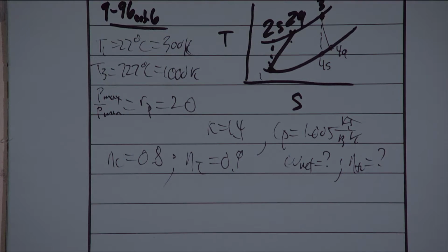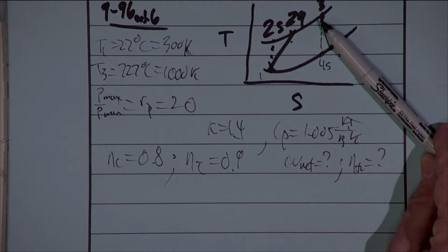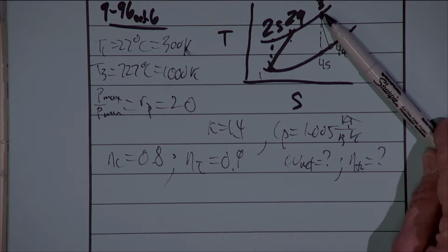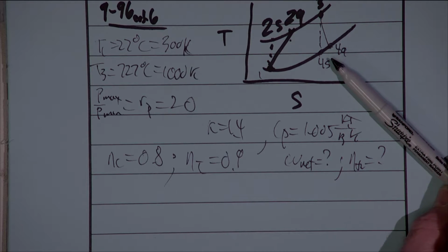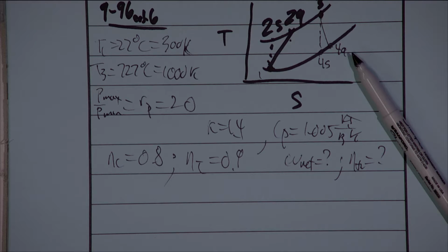Now, we had actually already seen the problem. It's still over here, but I'm going to get rid of that right away. We understand in this problem that this is a non-ideal, yet still simple air standard Brayton cycle. There's a compressor acting from 1 to 2. There's a heat input device, the combustion chamber, acting from 2 to 3. We've got our turbine from 3 to 4. That's our work output device. And then we reject heat into the environment from 4 to 1, but we really do not need to quantify that. So this is the basic cycle, right?